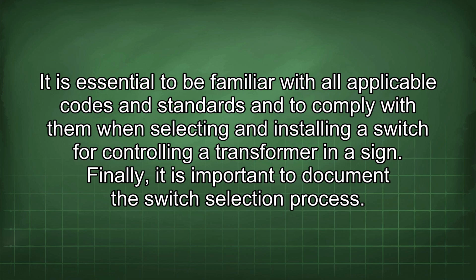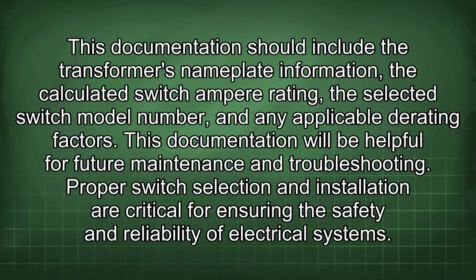Finally, it is important to document the switch selection process. This documentation should include the transformer's nameplate information, the calculated switch ampere rating, the selected switch model number, and any applicable derating factors. This documentation will be helpful for future maintenance and troubleshooting.